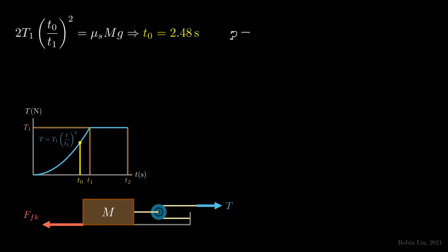The momentum of an object is denoted by p, and it's given by the mass times the velocity. The impulse J is the change in momentum, and the impulse provided by a known force can be found by integrating that force over the time period during which it is applied. The expression for impulse is why this problem lends itself well to impulse and momentum. Both the forces and the time over which they are applied are well known. It would be cumbersome to use energy methods since we don't know the distances over which the forces are applied.